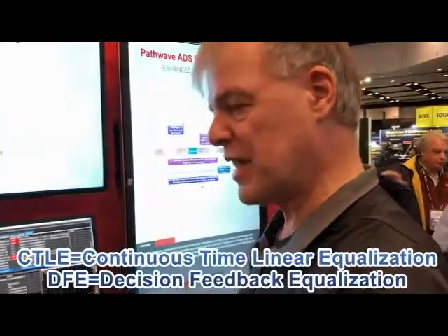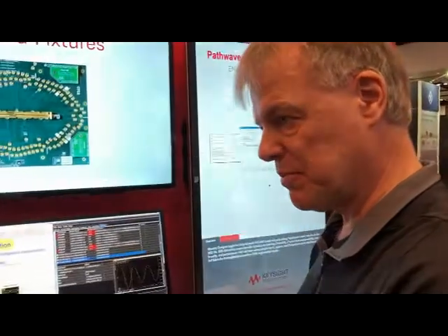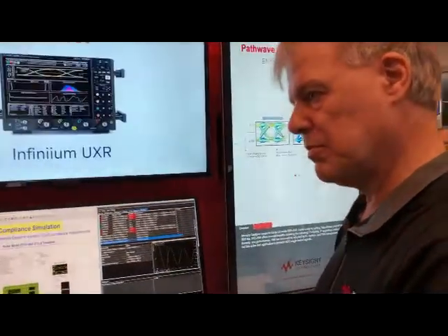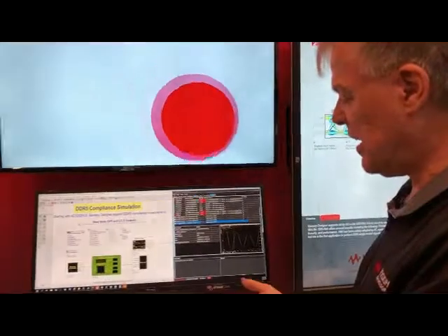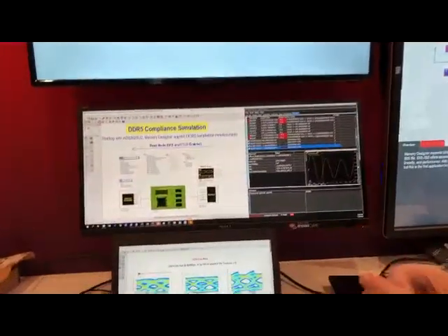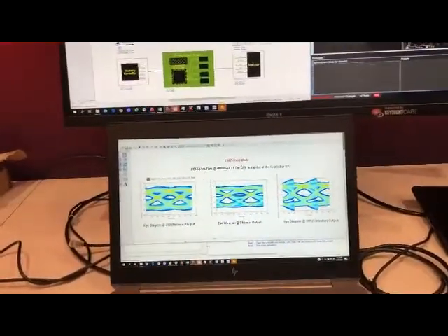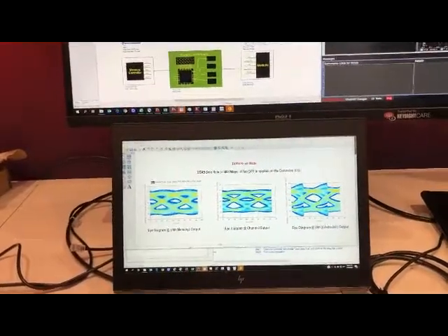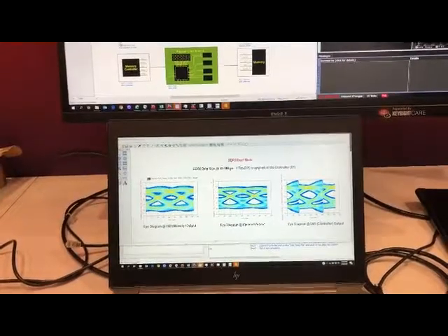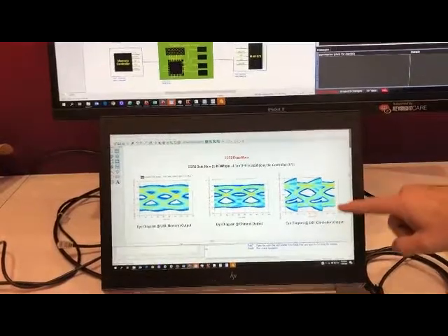We're actually looking at receivers that have what we call CTLE and DFE equalization built in, and AMI is our mechanism to describe that. Okay, and why do they need the CTLE and DFE? Because of the enhanced speed, you'll see down here, what often happens is that through the channel, the waveform will be degraded and the eye will be very closed. Okay. So what you need to do at the receiver is to apply a correction, we call it equalization, which then will open the eye.